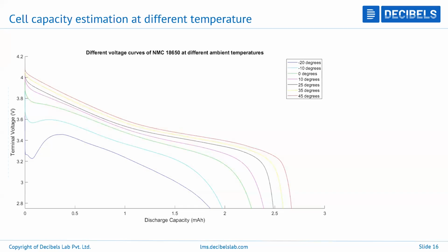The second question: what are the possible side effects of using the cell at low temperatures? At low temperatures, your internal materials can start to degrade, and the internal electrolyte can start to freeze up and cause a lot of problems to the behavior of the cell. It can cause the internal resistance to rise very sharply, and because of that, degradation is very fast. I see up to 66% have chosen the first option, and that is the correct answer.